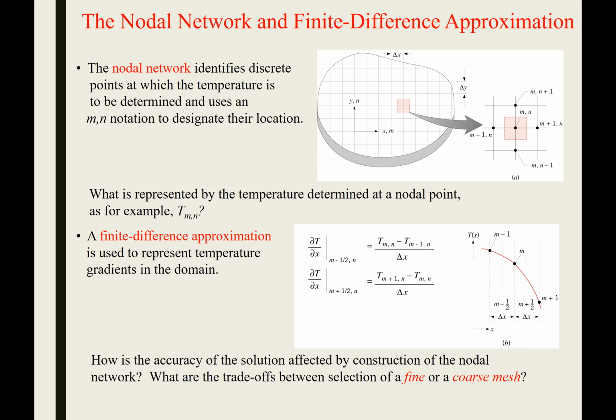You just define a control volume, you put on your energy accountant hat, and you start figuring out how is energy getting in and out of each one of those little blocks. And if you get good at this and you have a really good systematic way of thinking, this can be an extremely powerful tool that can really approach the real solution as long as you make your control volume small enough and have a fast enough computer and efficient enough coding skills to solve it.